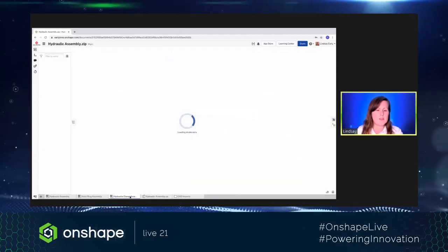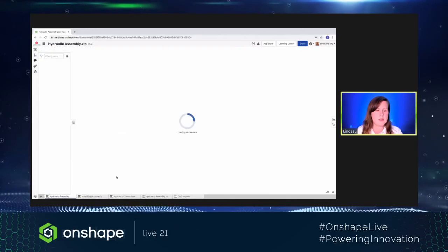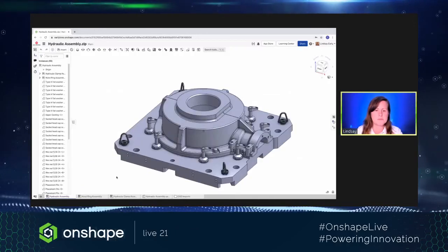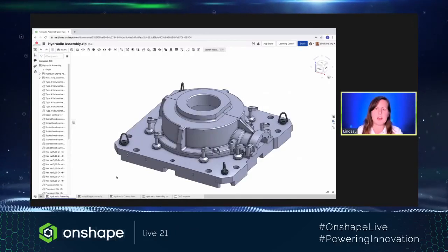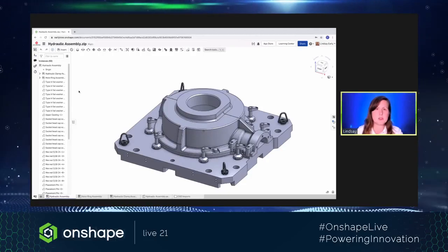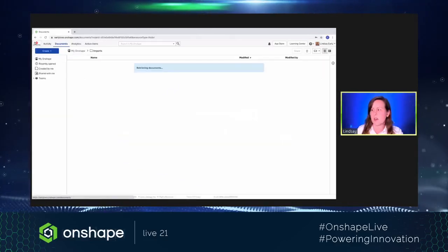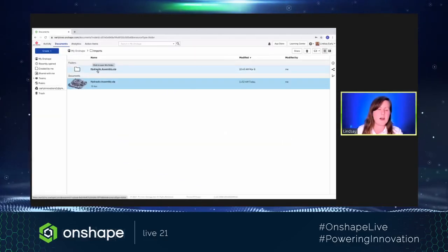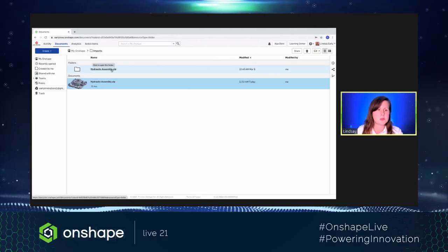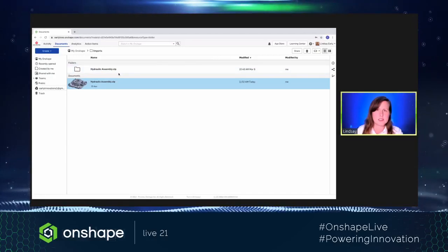And then you have the subassembly tabs that have all the subassembly information, and then you have your higher level assembly. So very similar, but you have that extra control with the assemblies. And your bill of materials will be correct. So now let's talk about the one that gives you the most control, which is importing into separate documents.